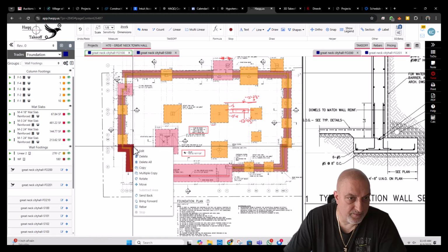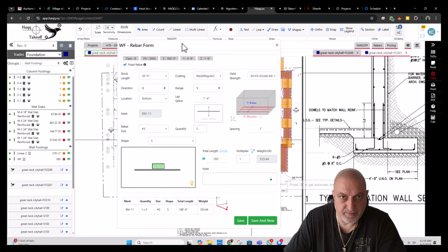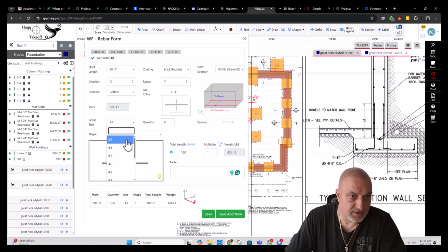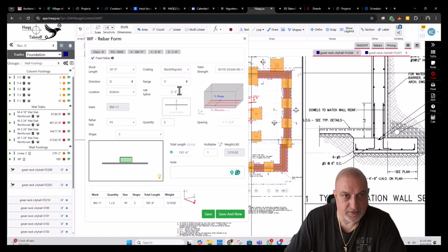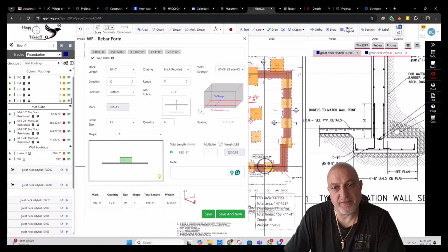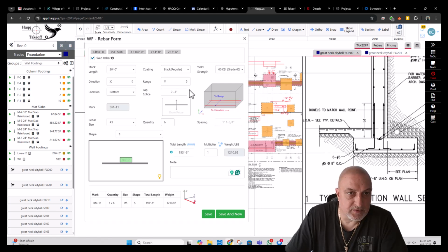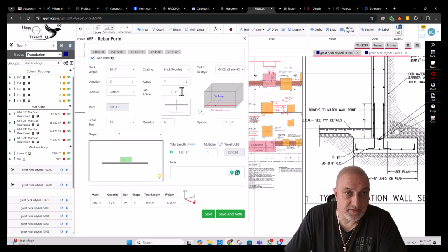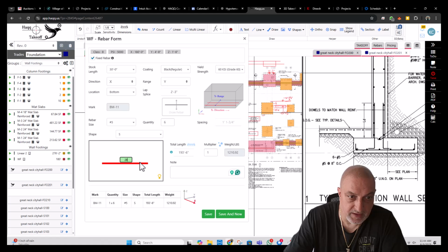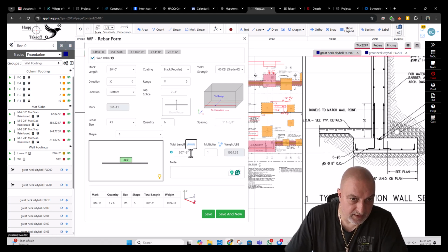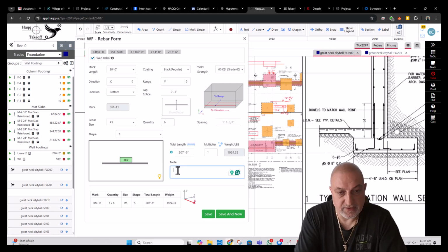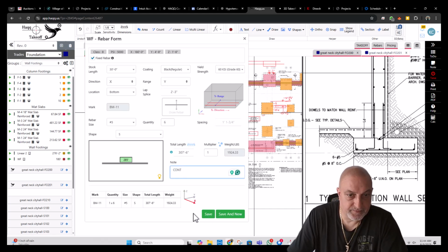Okay, now add rebar here. 6, number 5, and then number 4, 2 for 3, 276 feet we said. So I'm gonna add 5 feet more for the development length into this mat slab. 276, if I say 275, plus 5 is 280. Let's say 285 feet. And it calculates all the lap splices. And this is only continuous bars. So we got 285, 7 new.